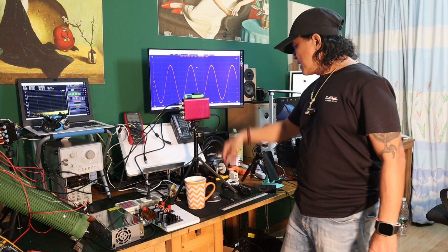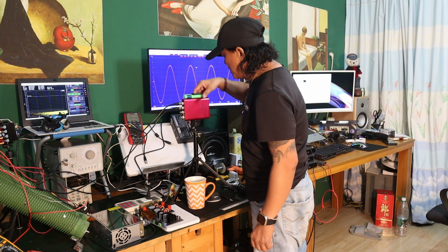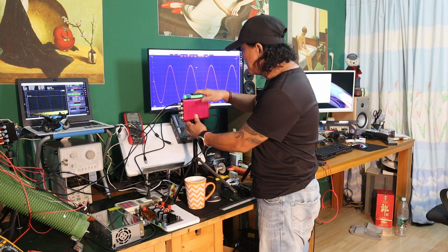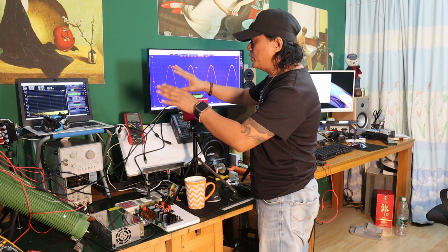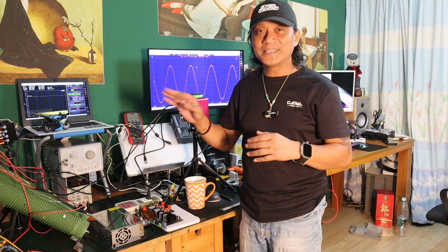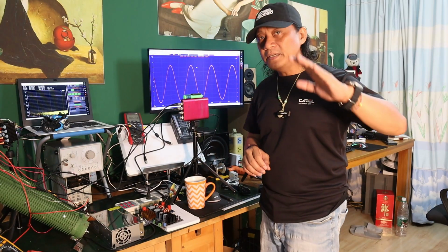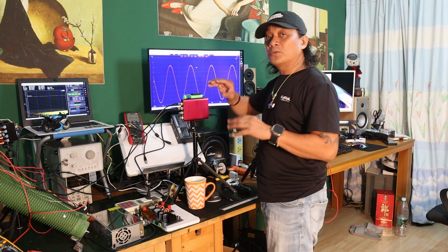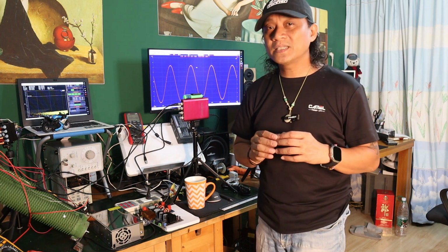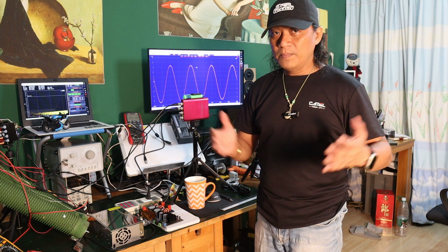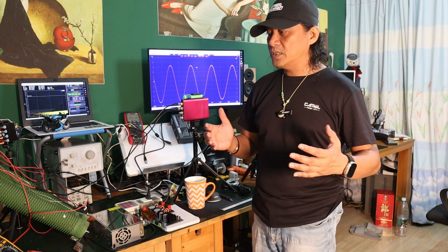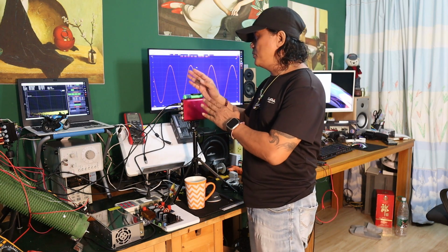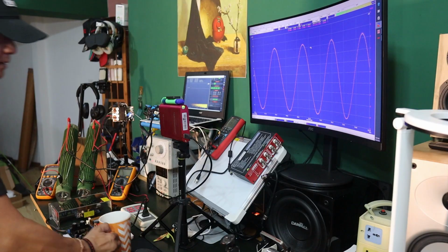So let me put it back into its place. I just use the tripod to re-emphasize it, and then put it together with the QA401 so I can measure the distortion. There is a distortion reading on the DSO 2A20E, but it's not so good. I mean, the distortion is not correct. It's quite high as compared to the QA401.